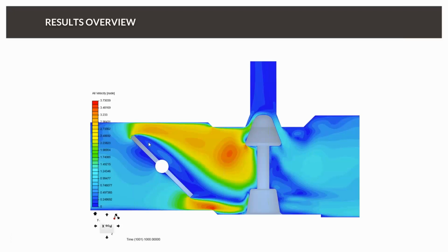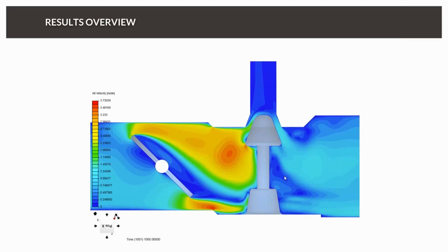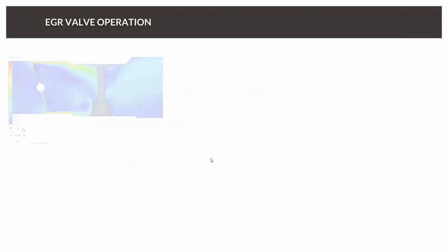And whenever it comes to mixing, and that's an important point, you can see that we have some wake here, which will definitely create mixing. However, for better mixing, I would prefer to have also some higher velocity gradients inside the flow. And here we have high velocity, and therefore, where the velocity is high, according to the law of Bernoulli, the pressure is low.